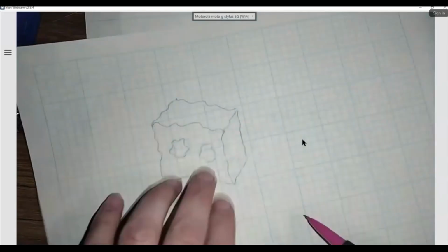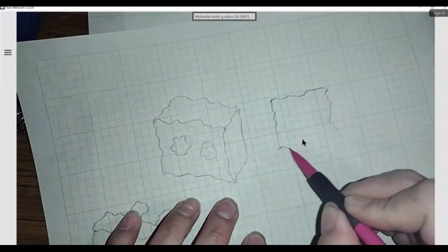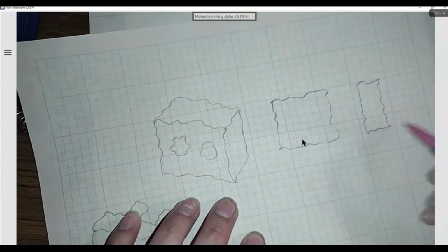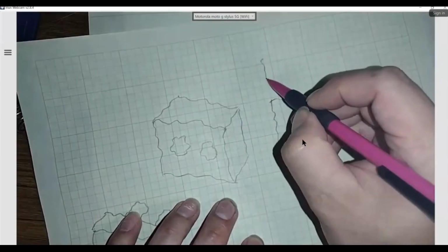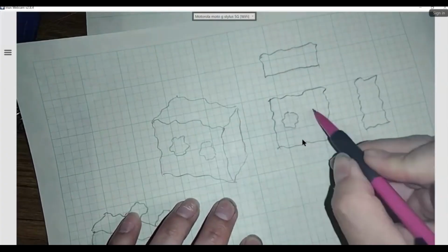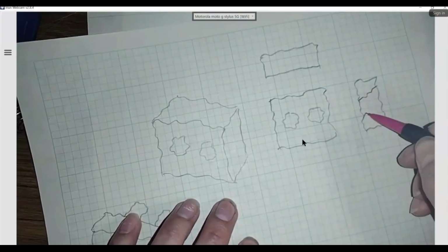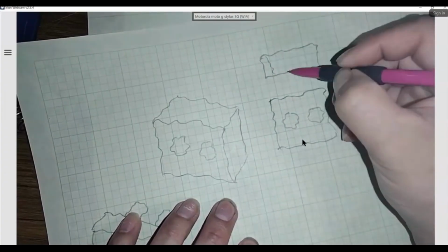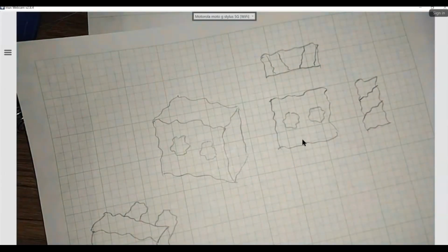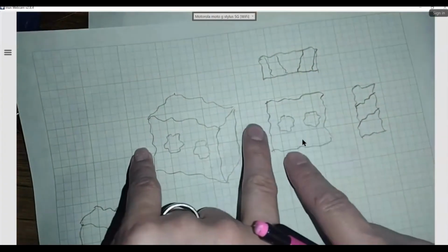First of all, if I were to look at this one, my front view will look something like this, and the side view will look something like this. I can also do something similar in the top view. I have one hole that looks something like this, and maybe my holes are crooked, somewhere like that, and this one might be a little bit crooked that way. You see my holes all crooked? I want to ensure that the holes are related to each other and that they are related to my datum.